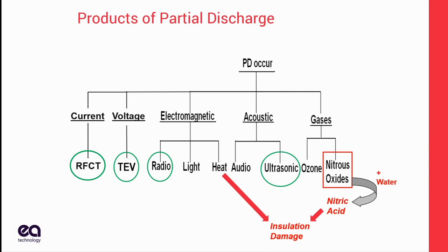So we can use these radio waves to detect PD as well. Now, a lot of our power systems, shielded cables specifically, metal-clad switchgear, transformers, are surrounded by a Faraday cage. So we don't get the radio waves out of them that easily. So radio has its place more in open air substations, but it's a good way of detecting PD.